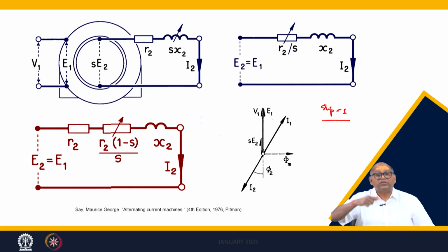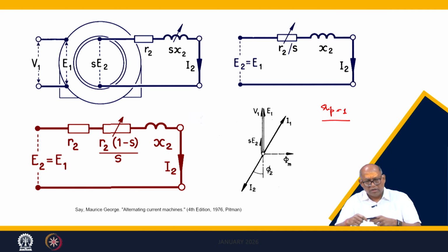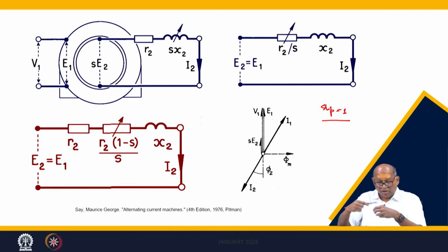So the rotor turns induce voltage and as a result there is current. So there is 3-phase balanced current. If the stator has a balanced 3-phase supply, a constant magnetic field is rotating, so it will cut the conductors of the rotor, and a balanced 3-phase current will also be created there. It is a law of nature that they will try to oppose the very cause. Therefore this balanced 3-phase stator and balanced 3-phase rotor can be brought down to just single phase.